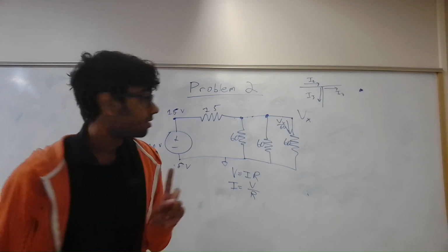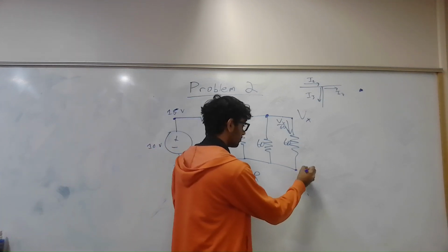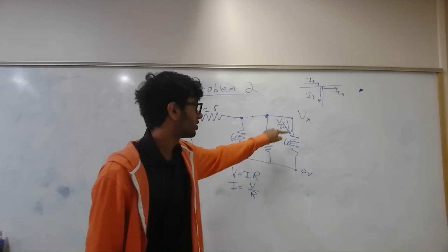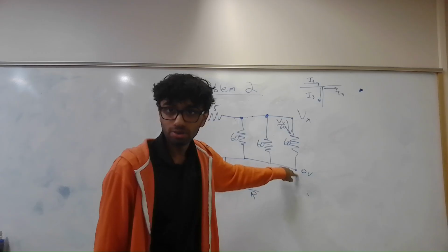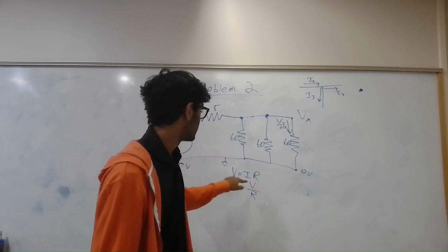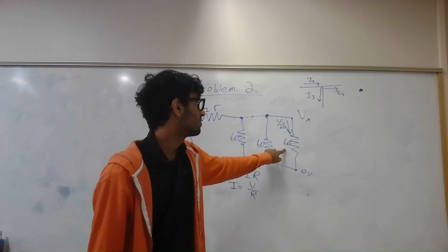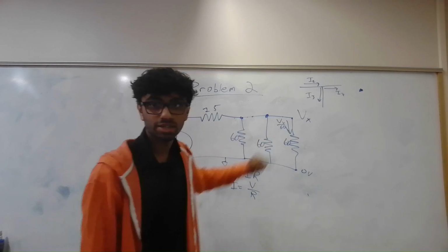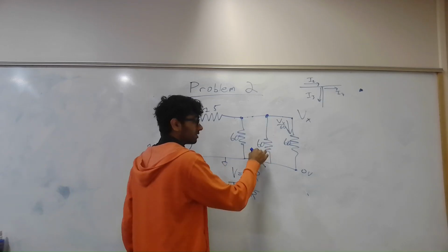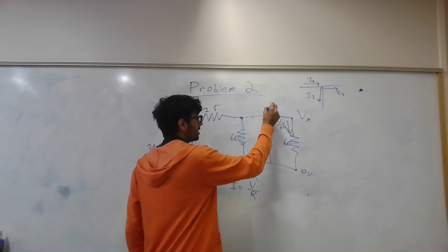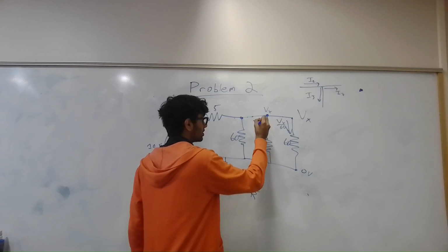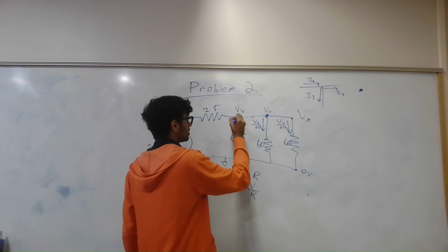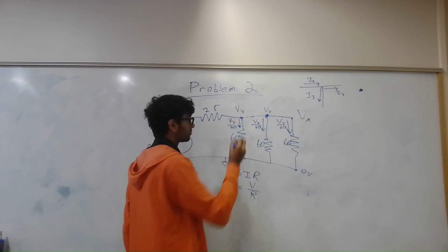Now, remember, we're assuming the voltage right here is 0 volts because we set that point to ground. So the voltage dropped by this resistor is Vx minus 0, which is Vx. So that's the V. The R is 60. And so now we can get the current through that resistor, Vx over 60. Same process here, because the voltage is Vx right there, the current going down is Vx over 60. Vx right here, so the current going down is Vx over 60.